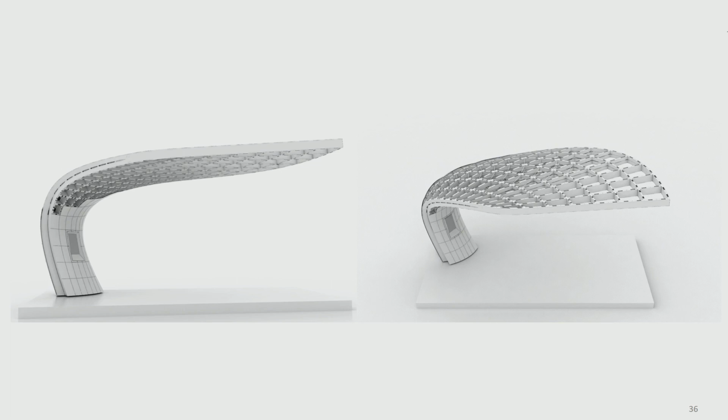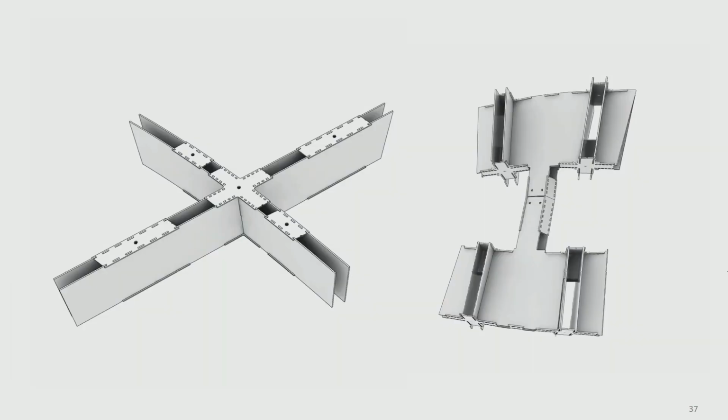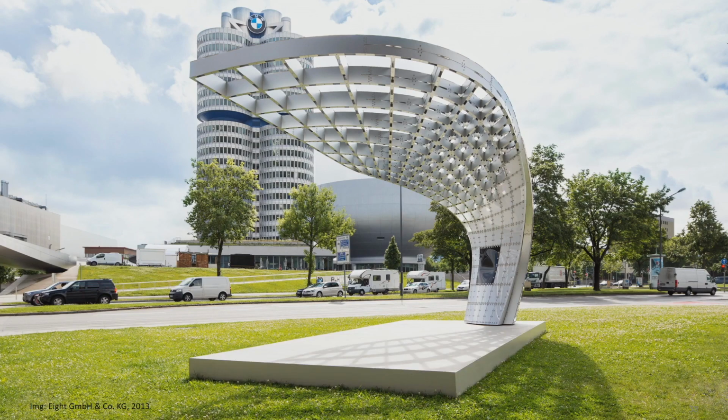But what became clear was that besides the material behavior and geometric constraints, such as that all the surfaces needed to be developable, that they had to intersect in certain points, the assembly sequence played a major role in the successful buildup of the structure. So the details and the entire geometry were developed such that every part could be reached during the assembly in a given sequence, and such that they fit together like a puzzle and force the material into the required shape.